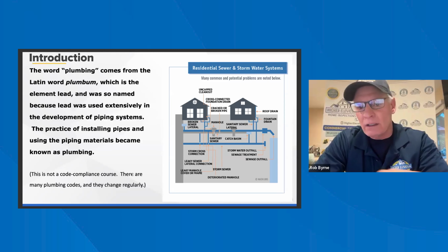Just remember that. Okay, now as a home inspector, we are required to check functional water pressure. We're not required to put a gauge on, but to check our functional water, we turn on cold at the bathroom sink. We'll turn on cold at a bathtub. This is one of our biggest water usage. And then we'll flush the toilet and see if we see a drop. On this house, we're not seeing a drop in water pressure. So that would pass a functional water test, water volume test. So that's how we do it. And you are required to have two operating at the same time to check for our water flow.